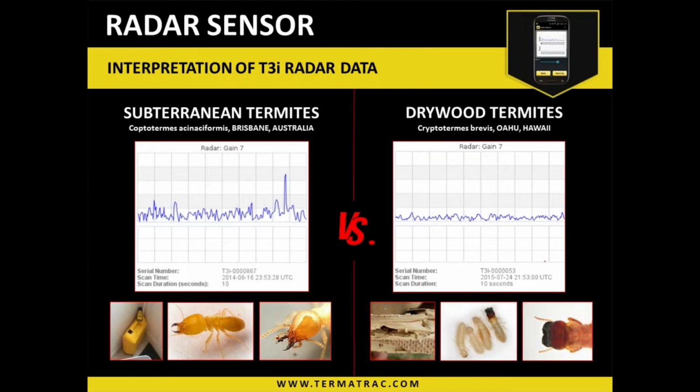What we see after doing that tap is an increase in activity as presented to us via the patterns. The patterns will become more intense. Then after a moment, the termites will realise that it was a false alarm, and they will come back into their normal formation and continue on. So after tapping, if we see that considerable change in the pattern, it's a fairly good indicator that it actually is termites.